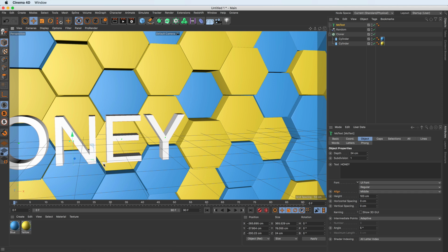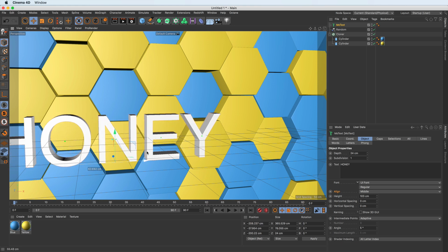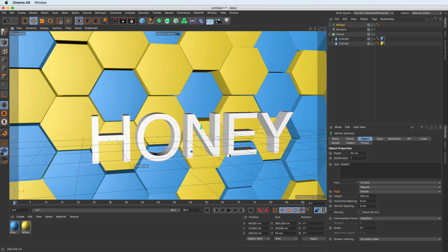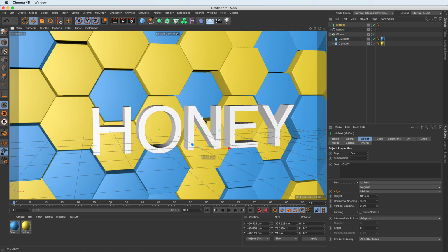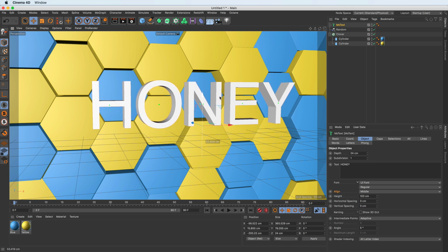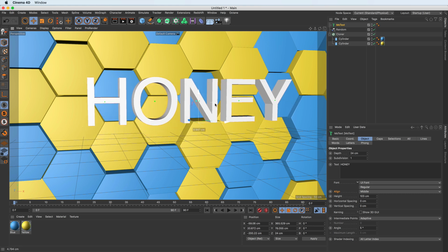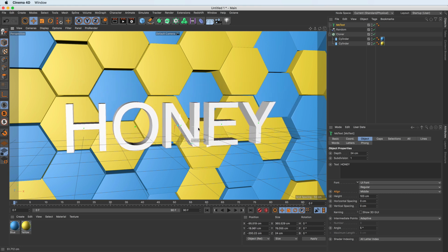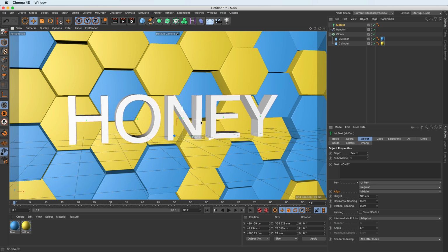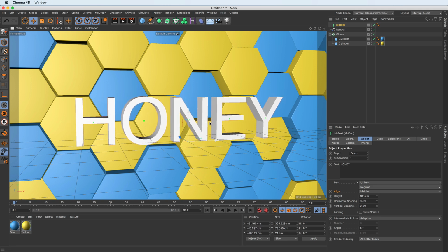And now I can hover over this X arrow and constrain movement in the X, and then constrain movement in the Y as I hover over and highlight the green Y arrow here. And I can also hover over this little corner here, and when that's highlighted, this is actually selecting a 3D plane, and I can constrain movement in the Y and X 3D plane. So I'll place that right there.